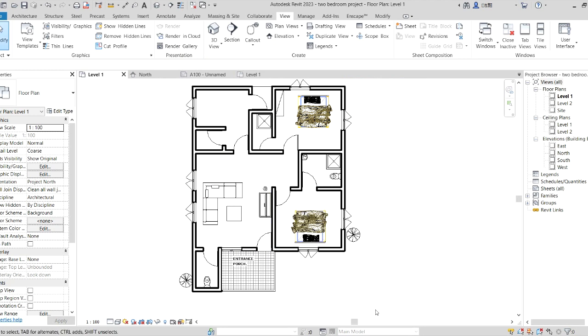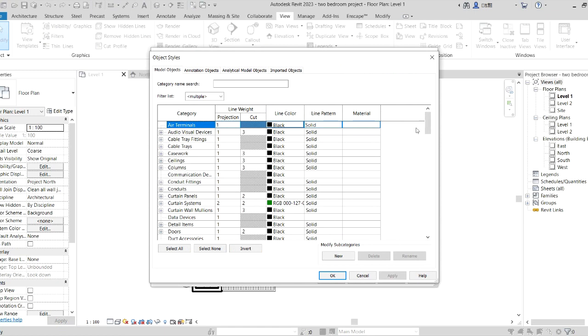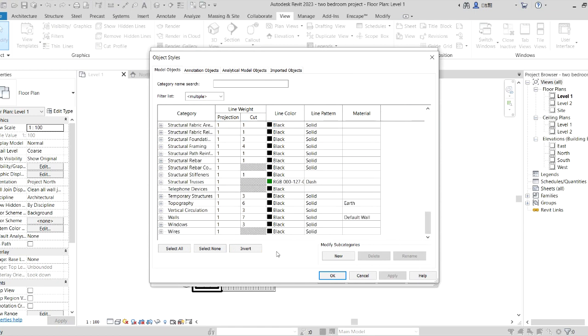And you see that the thickness has already been changed. But I don't like double thickness, I like a black line. So instead of going here to this visibility, on your keyboard just press VG. So Visibility will come out for you. You scroll down, then change what we want to change here. Instead of using 7, I want to return it back to the way I had it.